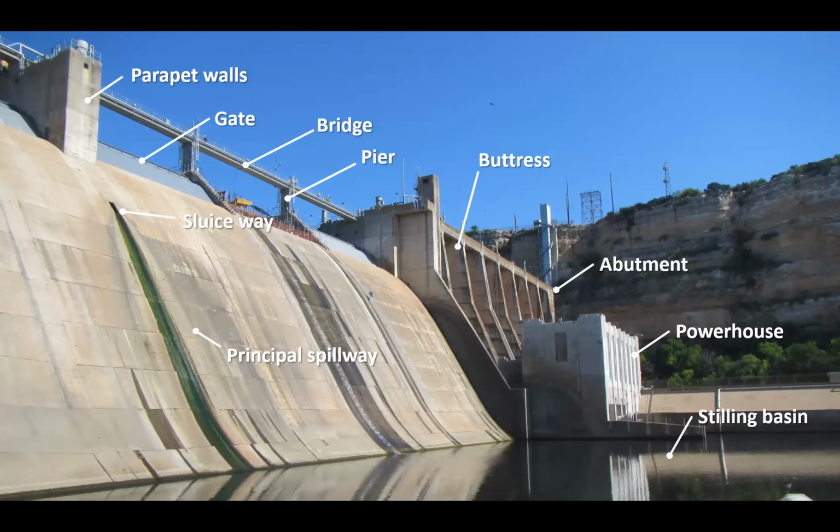I mentioned all the dam failures that had occurred in the last 9 years. A third of those failures were overtopping. So if you can imagine back to Harvey in 2017, we were very close to that situation with the Addicks and Barker Cypress dams. They were getting very close to being overtopped, and they went ahead and did a controlled release of that water in order to prevent any further damage to the dams.